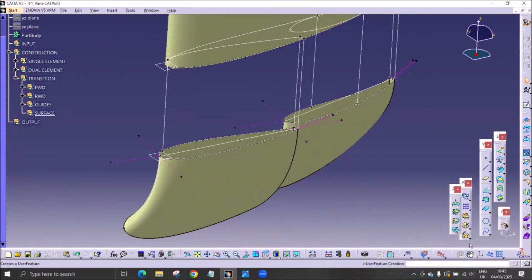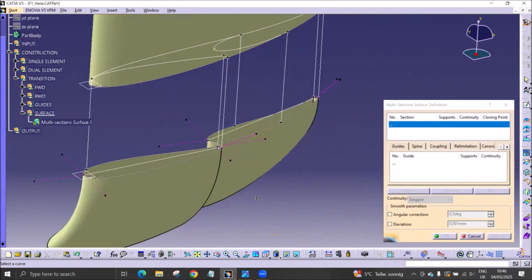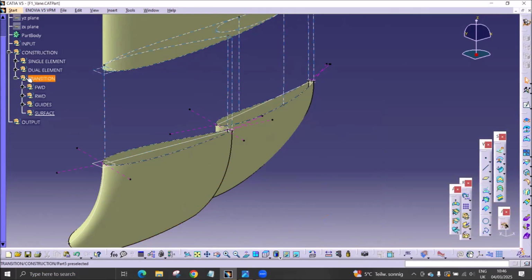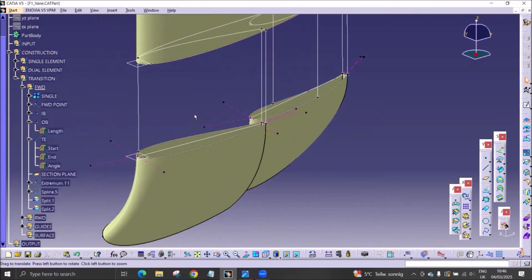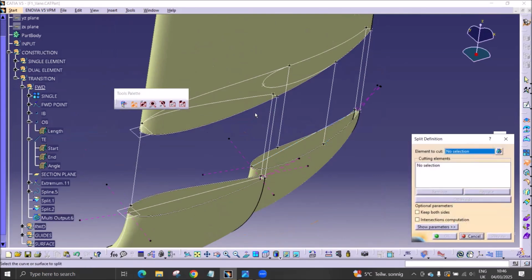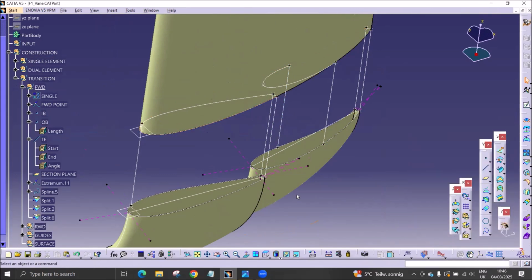We are creating a surface folder now. So you can see sections are defined in the upper part and guides in the lower part. You always need to decide what is a section and what is a guide. So we still need to split the upper part to what we need there before we can start. So again, in the forward folder. But this is relatively quick because we already have these points. We already have the profile here. Okay, so that's the outer side.